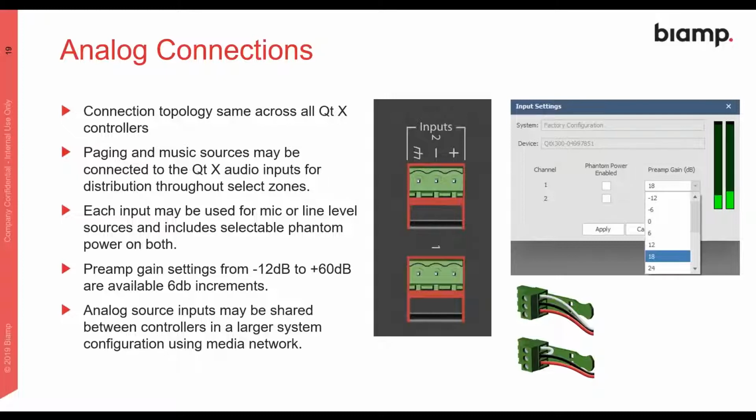They are selectable. So they're kind of like a source selector in Tessera, where you've got multiples and you're picking one of the two. When you set it up as a paging source, then you create logic that can trigger a ducking on a background music source as a page comes in. That's an important thing that's been asked a lot of times with support. We get a lot of questions about can we mix left and right audio and use those simultaneously? They are currently set up to be discrete, and you have to select between.